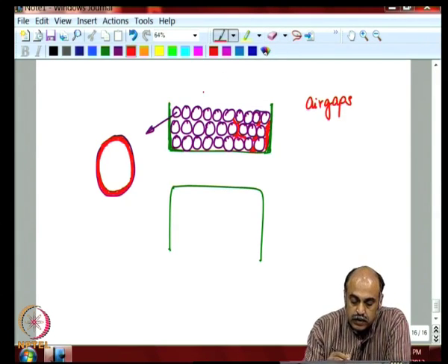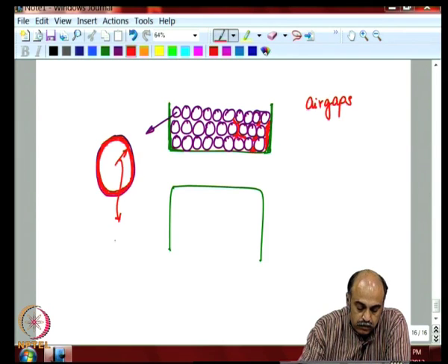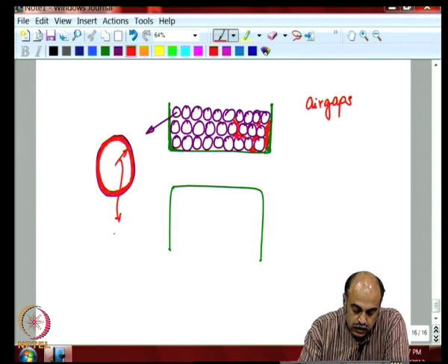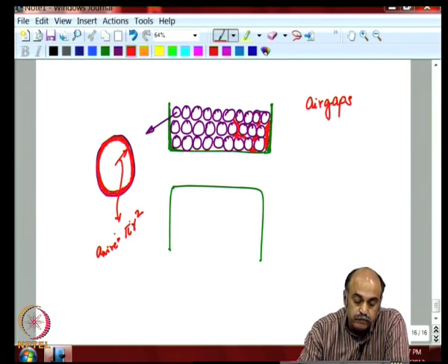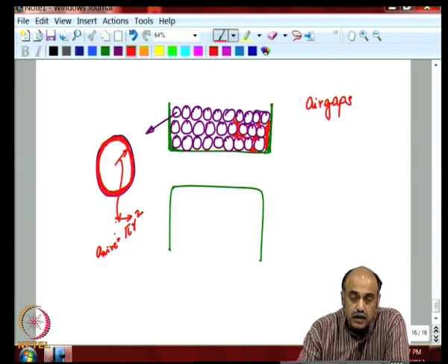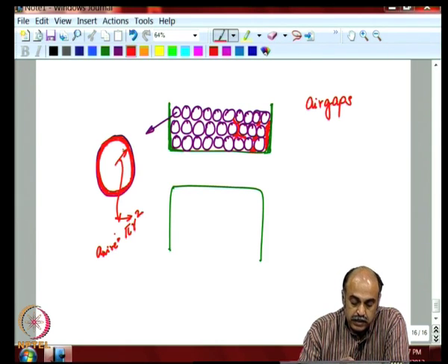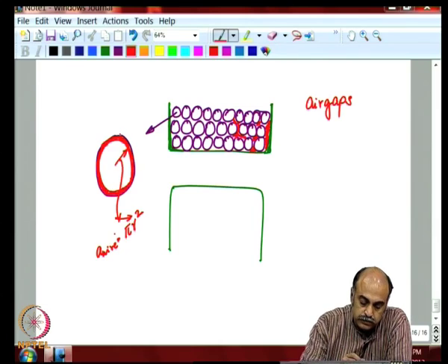So, therefore, the wire cross section, what we say as a wire, is pi r square, where this r is actually less than the total wire gauge radius because of this enamel which eats away some area.